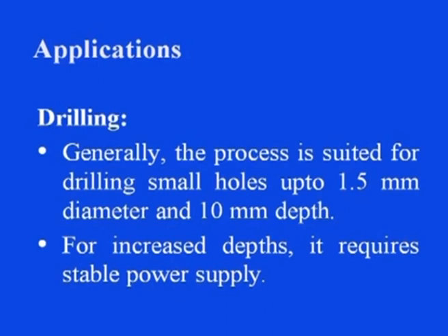For increased depth, however, it requires a stable power supply. With increased control, drills up to 19 mm have been reported. Inclined holes can also be drilled by this electron beam machining process.